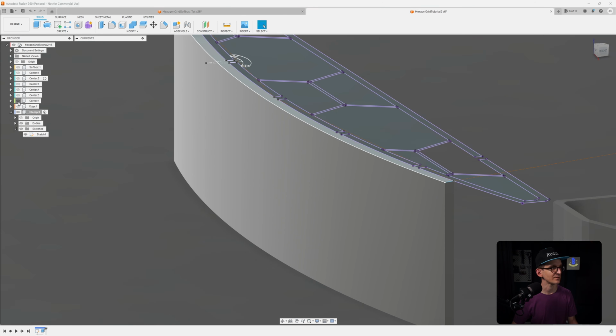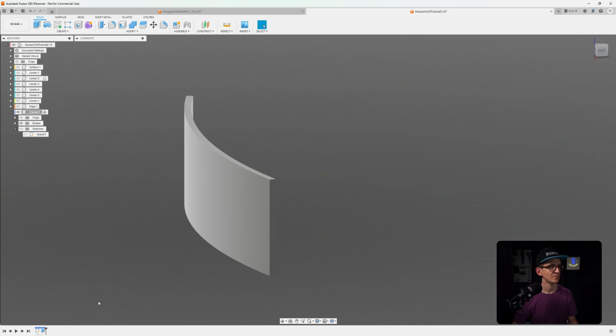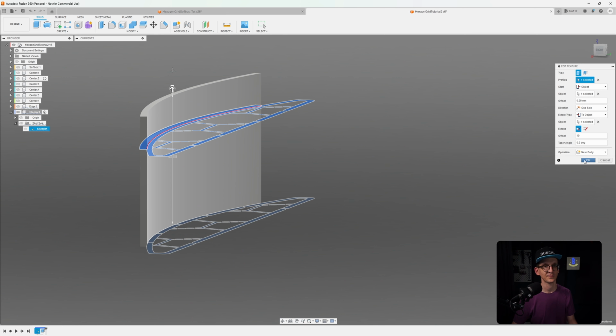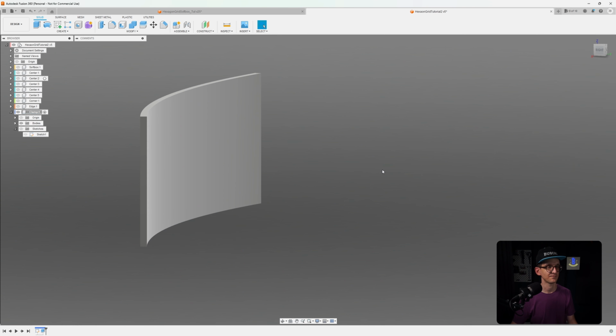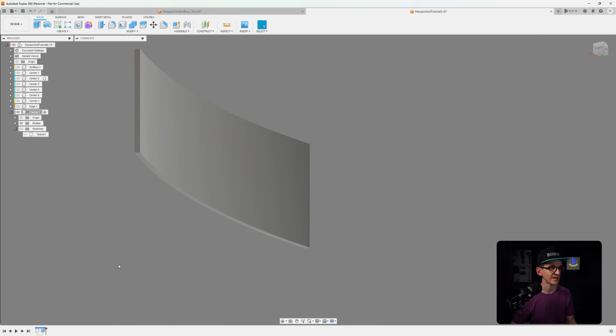Let me switch off the edge and corner for a second, and maybe also the sketch. But I know that the softbox is actually going, of course, beyond the grid, right? The grid sits in front of the softbox, so we need to reach further and then hook behind. So actually I can use the offset for that. Let's say, for example, 10 millimeters. That is more or less what I need here. And say OK.